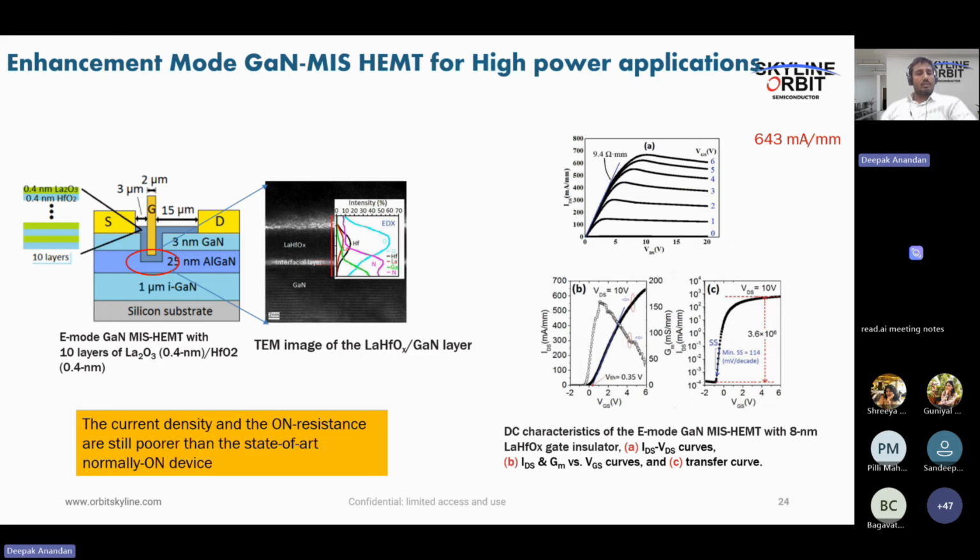And another one is they are trying to include the multi-stack layer of charge traps, so that when you have controlled the negative charge here, it will help you to deplete the carriers here. But nevertheless, still it can help you to achieve very high current, and threshold voltage will be very significantly low. Still, this device needs extra cautions to make the device turn off completely, because it's a very tiny voltage. Even for a small fluctuation it may have the chance that it will turn on and it will create the potential damage to the other circuits.